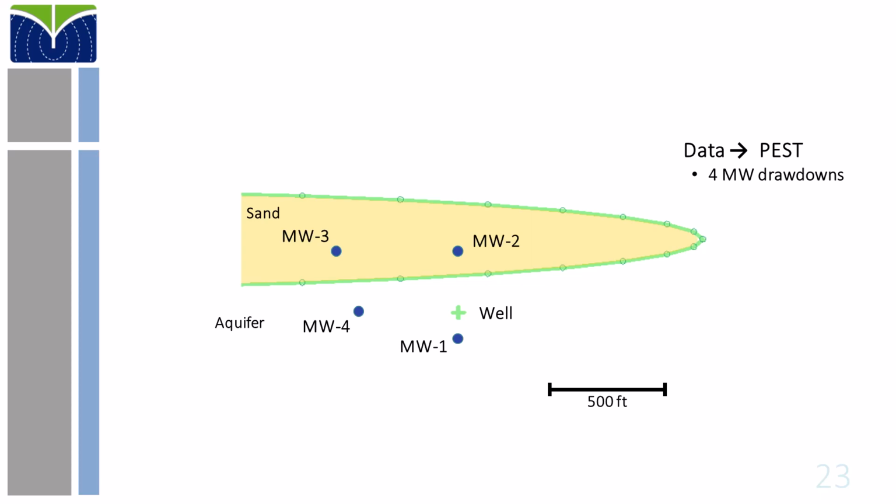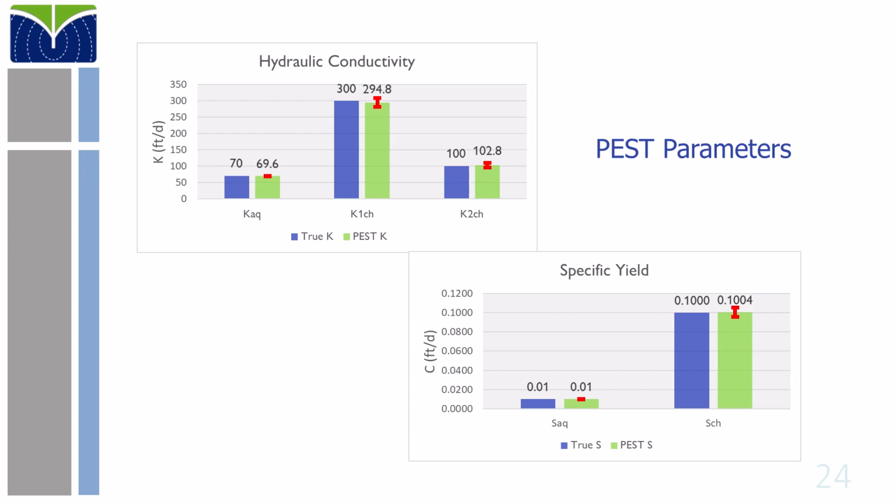As the pumping test progressed in the model, and the cone of drawdown expanded outward, this additional well measured flow effects coming toward the center of the drawdown zone and from north to south across the sands. This allowed PEST to generate good estimates of the longitudinal and transverse sands hydraulic conductivity values with reduced uncertainty.